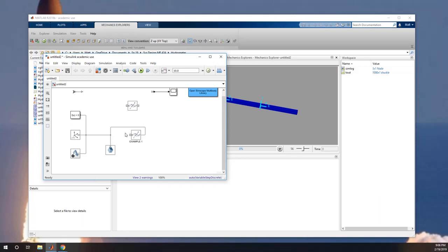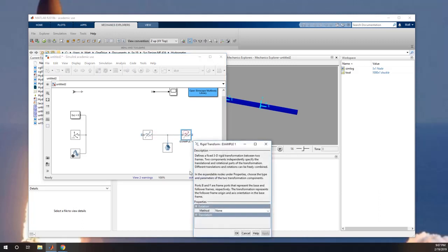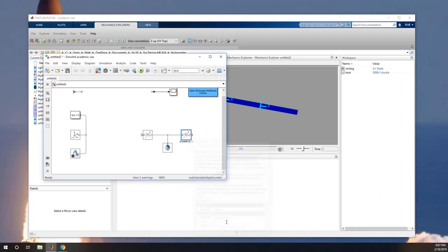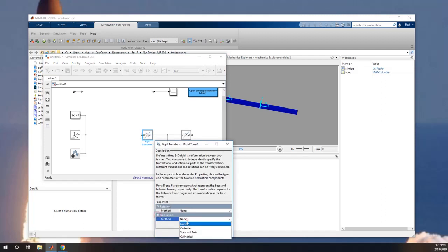So that's something to get familiar with, is if you're on the follower, you're going to be translating sort of the negative of whatever axis you select there. So that was just a demonstration of that. Now we'll continue here making our 4-bar mechanism. Connect all these together. Make sure that this is A over 2, positive x. Translate positive x, A over 2.